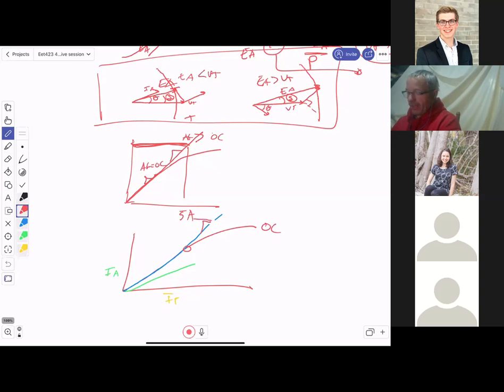So if you've got a reading of a voltage here at, let's say this is 5 amps, and your voltage, if I tell you your voltage is 200 volts on the air gap, and then I tell you the voltage on the open circuit characteristic is 170, you know you're saturated because these two are not the same. If I said, okay, my field current is 3 amps, and I've got an air gap voltage of 130, which is also equal to my open circuit voltage, because those are the same, right? They are linear. There's no difference between the two.